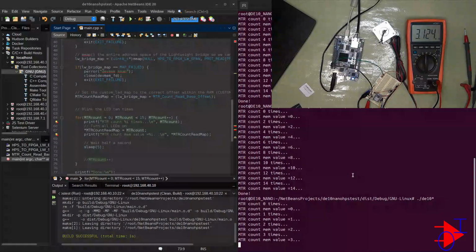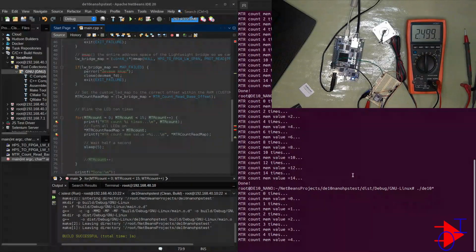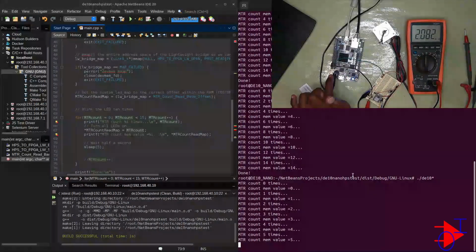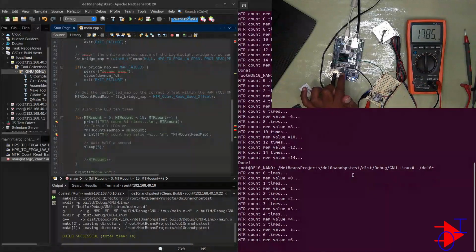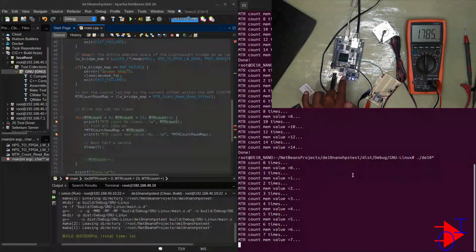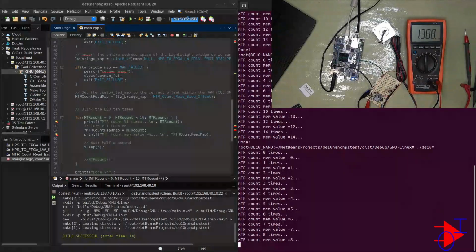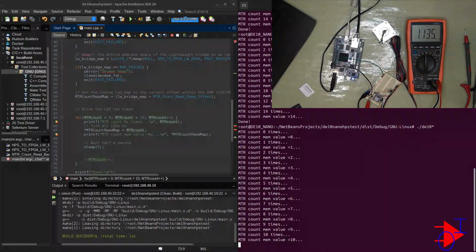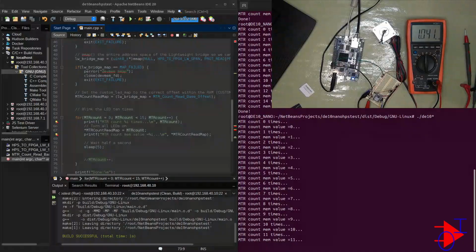And 3.1 megahertz. Okay, so the output is received and the FPGA is counting as it is programmed to do. The frequency, however, is high. So let's change that. And this time what I will do is just stop the video and compile and copy the RBF file to the SD card and come back to this again. So just give me a moment and we'll come back to this quickly.